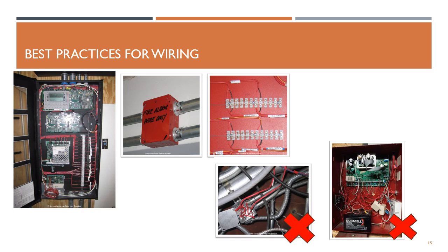The panel connections are just a mess. Everything is spliced and splicers are not used, and you will lose control. Also, in the picture above right, in the middle, we see a junction box of a fire alarm system that is properly marked. The box is red, and it has also been written that it is a box for fire alarm systems.